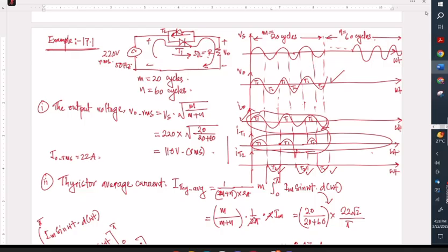So that's why this overall power factor, since it has the higher frequency components as well, there should be a displacement factor, harmonic factor and other things as well, for which your power factor will not be purely resistive, or power factor should not be purely 1. Rather, it will behave like an inductive load.